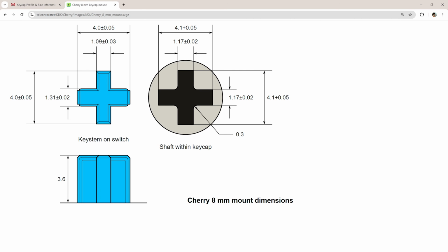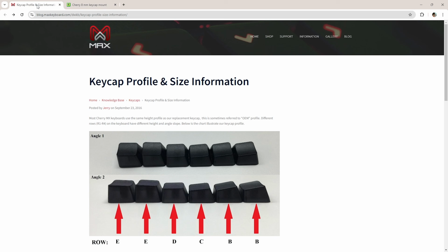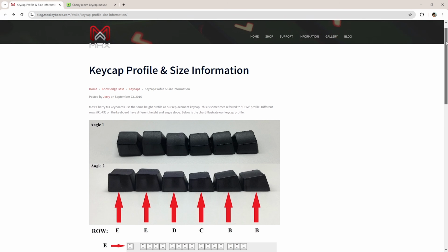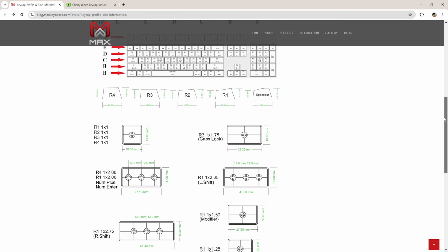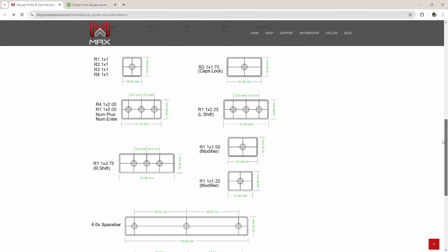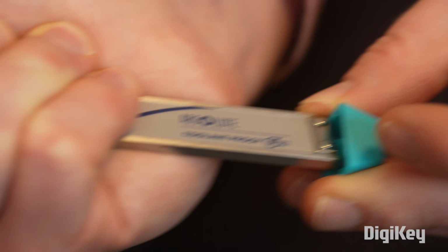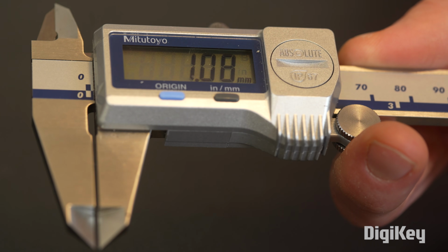For fun, let's make our own keycap for a mechanical keyboard. I've got Cherry MX switches on 2 of my keyboards, so these dimensions should, in theory, work. Notice that the keycaps have a slant to them, depending on the row. We'll create something that's symmetrical in both X and Y axes to make this easier. The internet can also give us information about the stems that mate with the switches. This stem height isn't exactly right, though. From what I can tell, the stem should be 1 mm from the bottom of the cap.